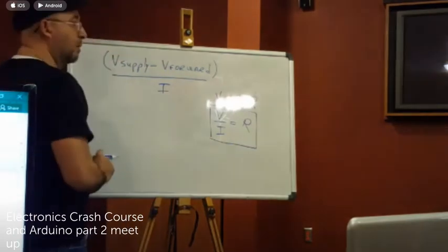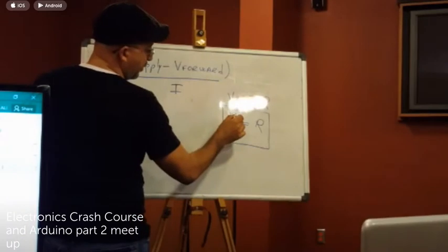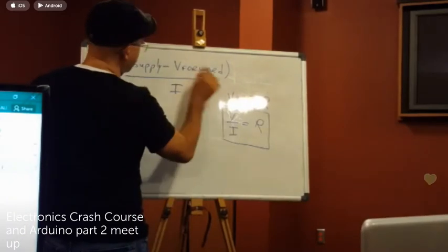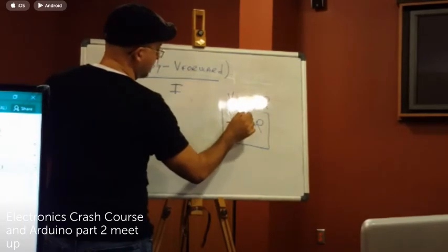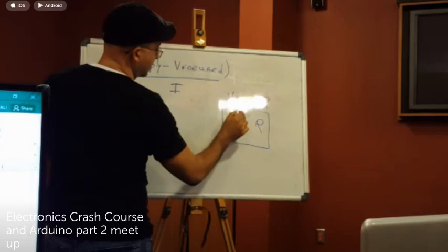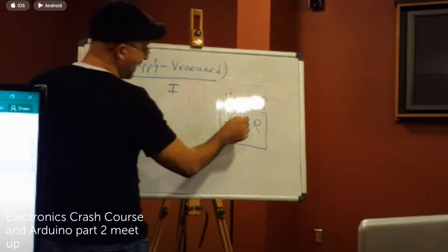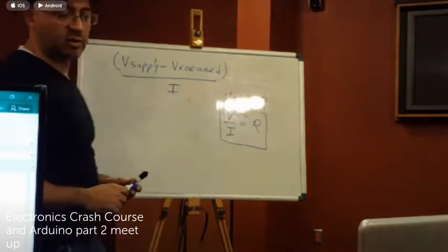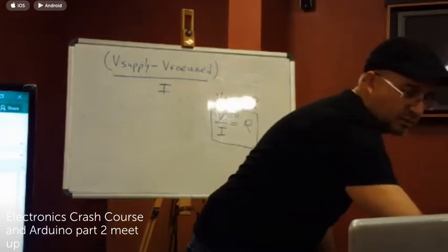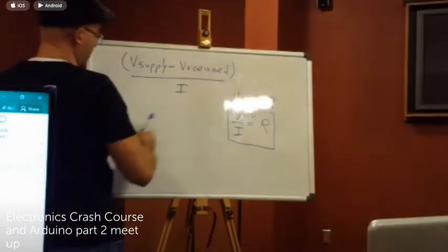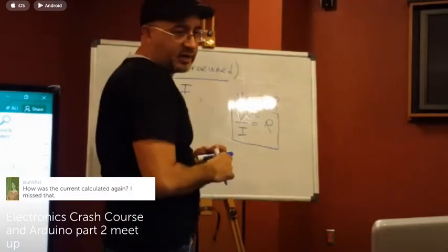This is Kirchhoff's voltage law. Very simple. This voltage, though, is that difference that we have right here. The supply minus the forward voltage. That's this voltage. And the I, which is the current. Now, all of these values come from the spec sheets of the manufacturer that created these RGB LEDs. So in this case, I'll put right here what the specs are. In this case, the red.